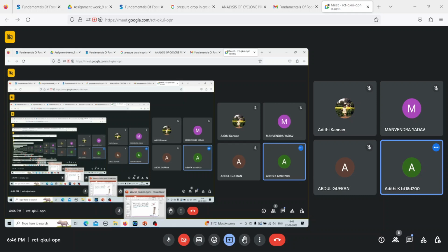Your starch particles, when kept stationary, will experience three different forces. One is the gravitational force, the other is the buoyancy force, and the third is the drag force. When you balance these three forces, that is Fg minus Fb minus Fd equal to 0, and simplify the equation further, you get the equation of the settling velocity. The equation has been derived in the video lectures and in previous problem solving sessions as well, so you can go through those to learn about the derivation.